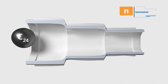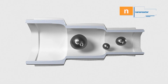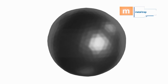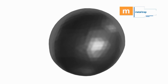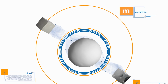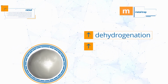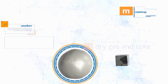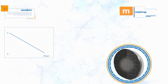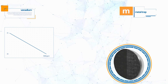Such interaction can be represented in the form of a three-stage reactor, where hydrocarbons with different molecular weights are cracked at each stage. The use of heavy oil residues as feed means that they contain heavy metals, catalytic poisons such as nickel and vanadium. Nickel deposited on the matrix surface promotes dehydrogenation reactions and increases the yield of dry gas and coke. Vanadium present in the FCC feed damages catalyst activity because this metal easily migrates through the catalyst, reacts with the zeolite, and destroys the crystal structure.